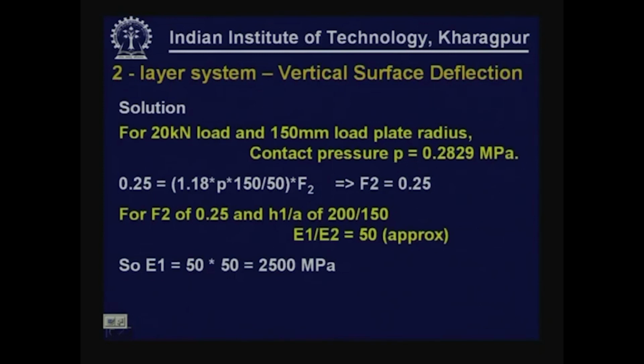So, in the case of two layer system also, if you conduct a plate load test and measure the surface deflection, and if you know the other properties such as the property of the subgrade, we can easily find out what is the modulus value of the pavement material.